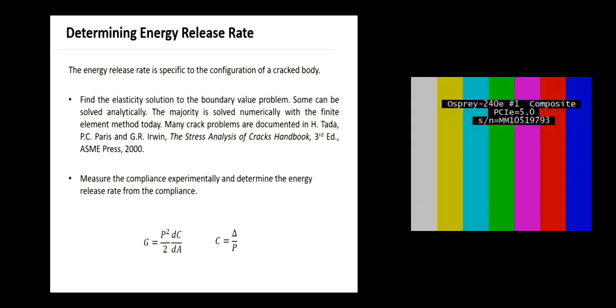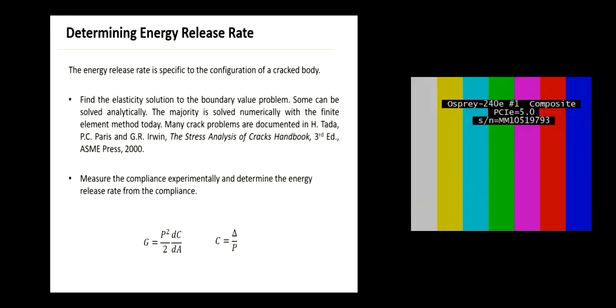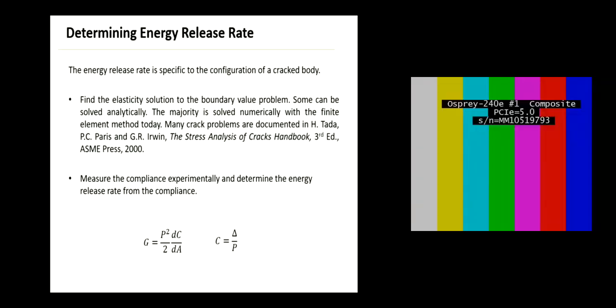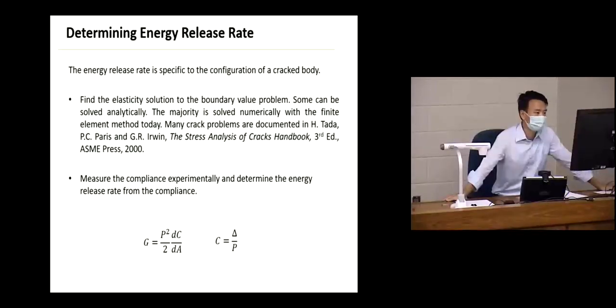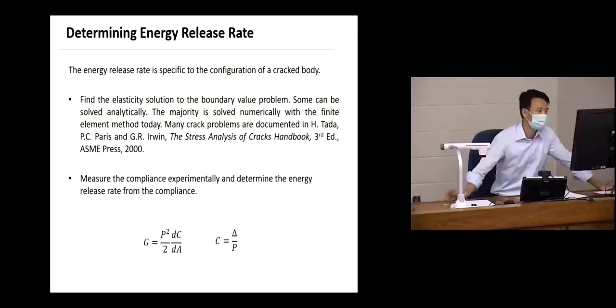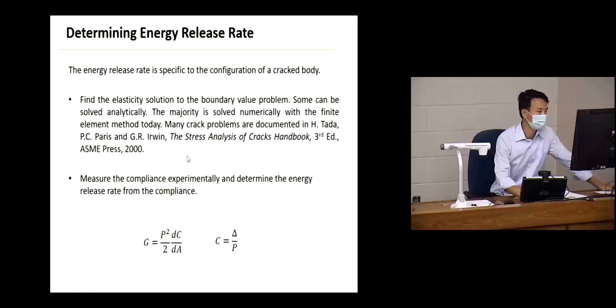And a lot of those results have been documented there, right? So there are energy release rates, how you calculate them depending on the geometry of the solid, the crack length, the dimensions of the crack, the dimensions of the solid, and so on. So you can do that. Most of the time we do finite element today, right? That's because it becomes very easy.